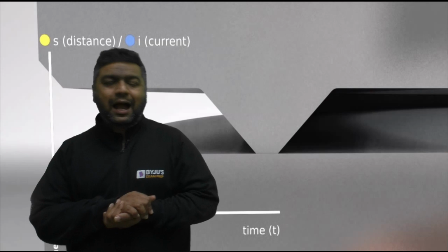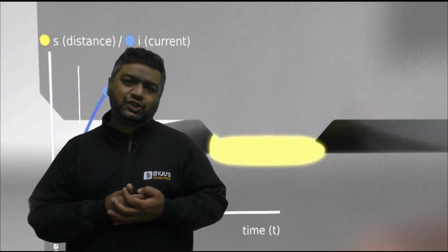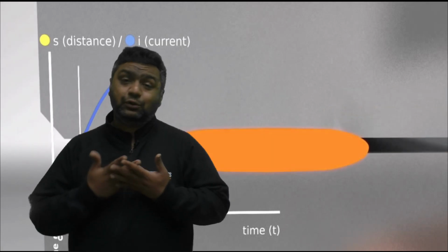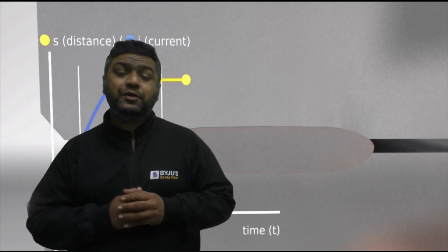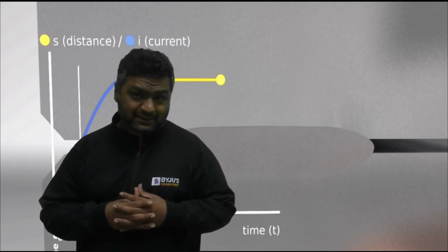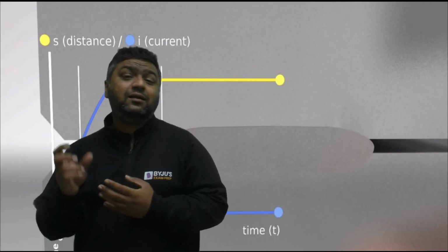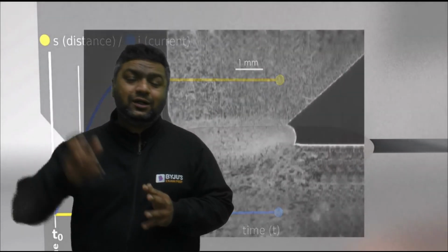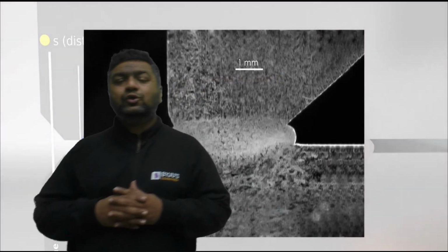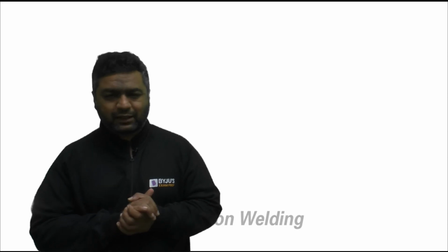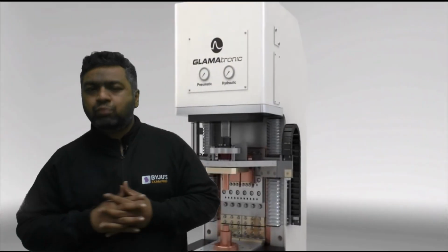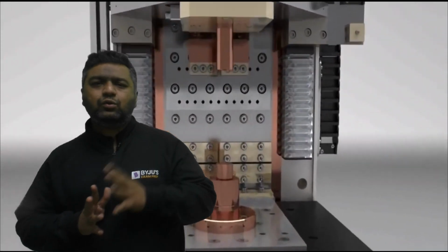Here we are going to make the projections on a plate. And my dear, when we are making the projection on a plate, as during the welding, plastic deformation of the projections would be taking place. So either we need to select the plate for projection, either whose thickness is more or whose conductivity is more. And I would also like to tell you, in the resistance projection welding, projections are made by embossing process, which is similar to the coining process.